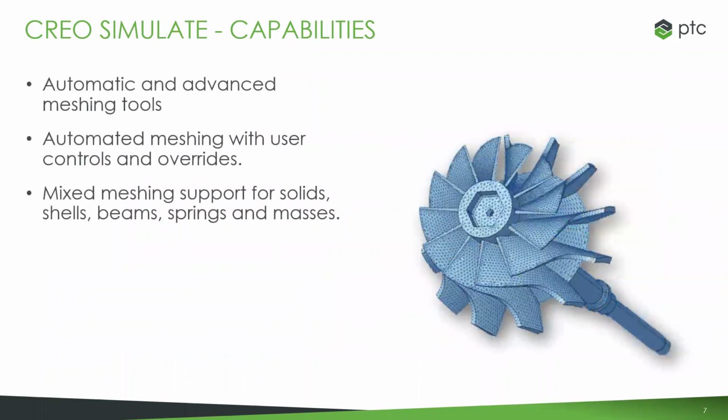Okay. Now, when it comes to meshing, a lot of times this is considered to be a specialty. There's meshing experts out there. This is like their worst nightmare, but Creo Simulate's all about automatic meshing. We just let the system go and do it. It's going to optimize the meshing for you. So it basically refines it in areas it needs to be refined in to give you the best results.